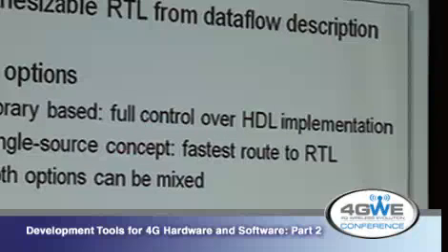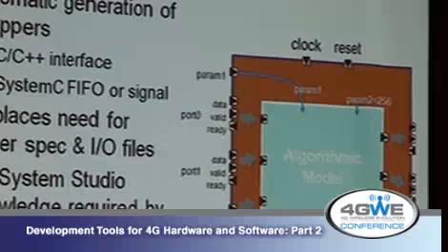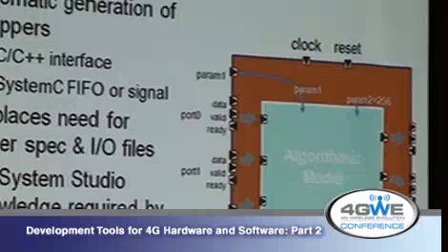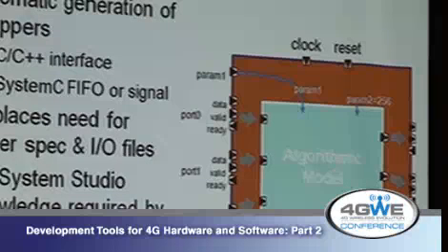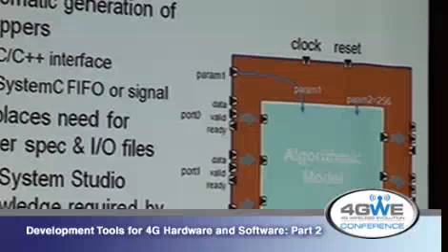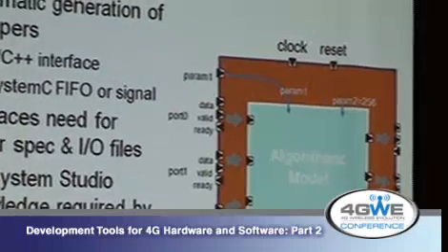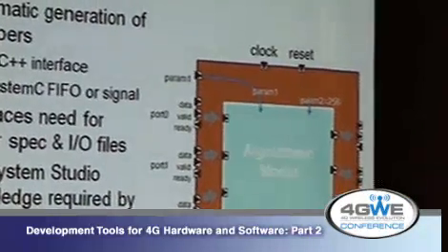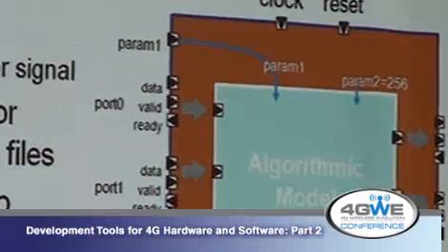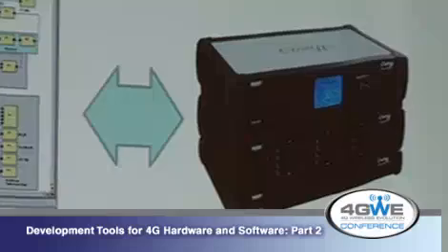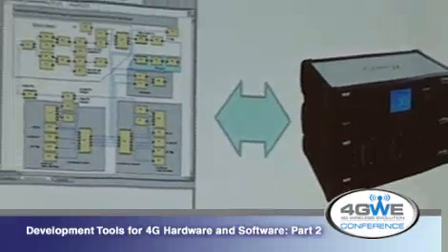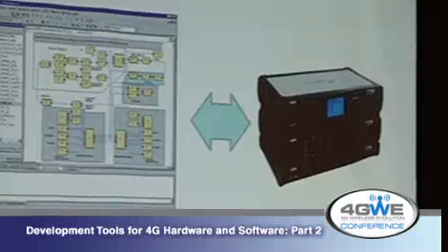And we have requests to basically either do high-level synthesis or be able to generate at least the HDL co-simulation for verification and do some level of translation here. So here you see one of those components where you have a C++ interface which we automatically generate around the algorithmic model to generate a SystemC wrapper so that you can import that into your simulation. And as I mentioned earlier, this is a real knowledge transfer, right? So there's no knowledge of the higher level model. It's really necessary once you go to implementation.